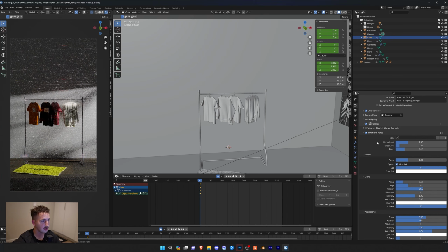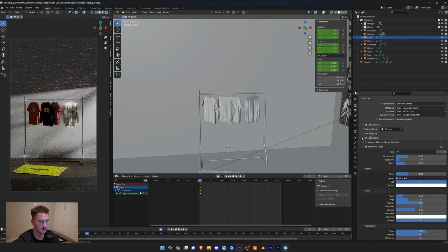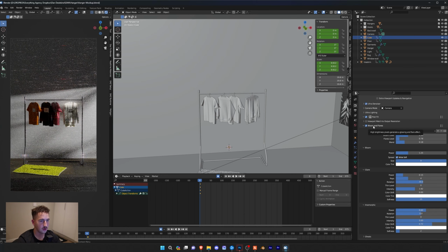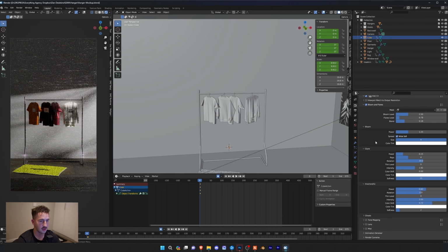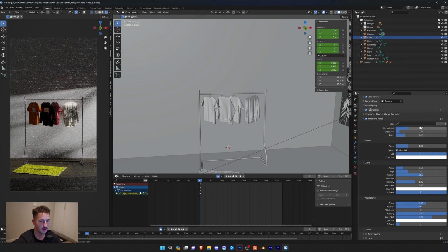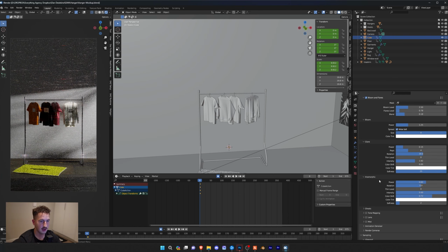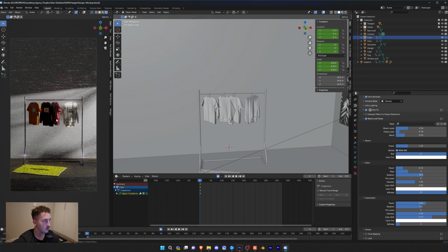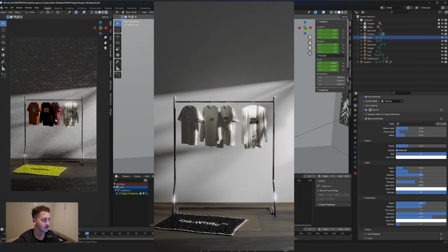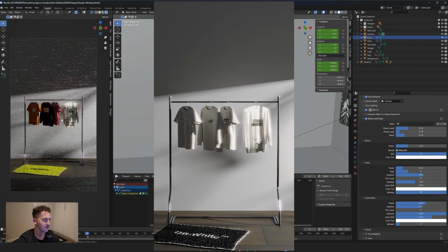But all your settings are going to be over this post effects little tab. So you can just open up this, and we're only going to be using your bloom and flares. So my bloom is going to set to 1.25. My bloom level is going to be set to 2.5. Glare and anamorphics is going to be at 0.15 and 0.6. These are the only settings that I did change. And when you render it out, you should get something like this, which I think looks really cool and it's a little bit more artistic.